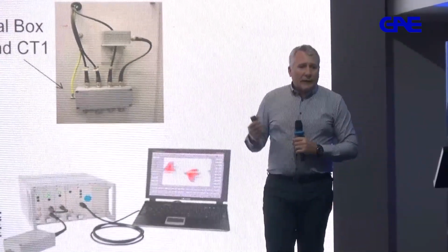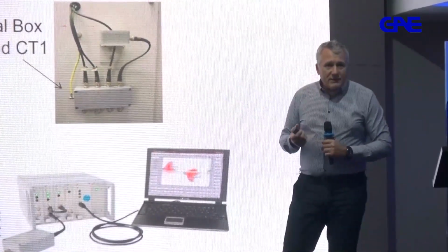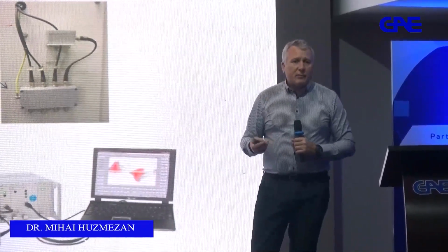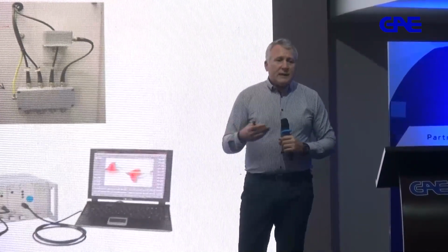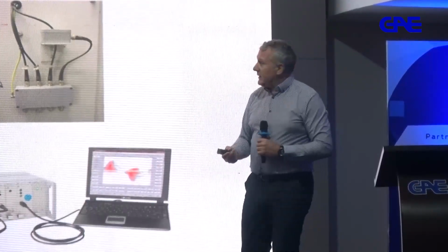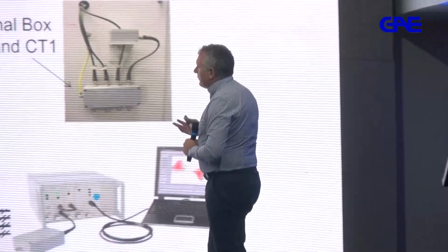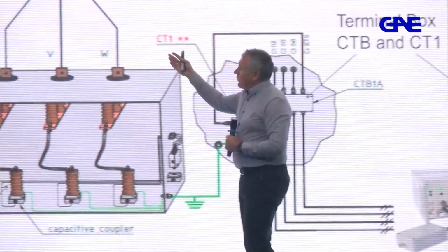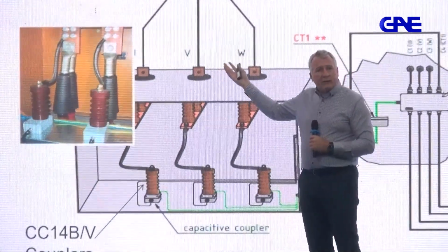Now, rotating machines, I mentioned to you, are also subject to the same issue, right? So you have high voltage, you have partial discharge, and it's a good idea to look at the quality of the rotating machine you have received, be that a big motor or a big generator, okay? These things also get repaired, so it's very important to carry out partial discharge testing. So naturally, during those times you will have the rotating machine, and of course, you would like to acquire the information from it.